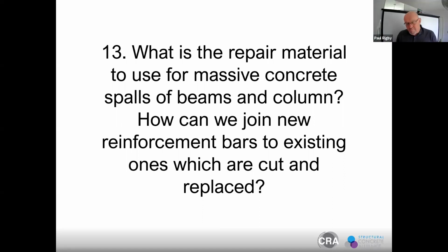Yeah, for mass concrete repairs, a large volume reinstatement, flowables are good, which are classified as micro concretes. Recasting concretes is another terminology you could use. Cubic meters can be done, pumped or poured within hours. Also spray concretes, wet spray, dry spray options. You can spray 3 to 4 cubic meters within an hour. So it's a very quick install.